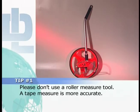Duro-Last strongly recommends against using roller measure tools because they do not always produce accurate results. But if you must use one, don't let the roller jump or skip as you walk across the roof. Roller measuring tools are not recommended for use on ballast roofs. This causes inaccurate measurements that could cost hundreds of dollars or cause you to over or underbid a project because